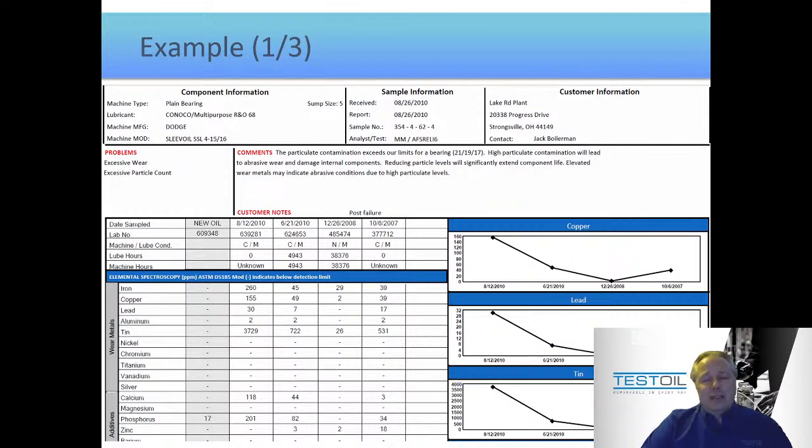So with this one, we now go down to the next section of the report, but still above the oil analysis data. So if you look here, we've got these sample dates, which are very inconsistent. There's 14 months between the first sample and the second sample. There are about 18 months again, and then just a matter of a few weeks. So with this type of erratic sampling, it's hard to predict what kind of trends we're going to expect to see.